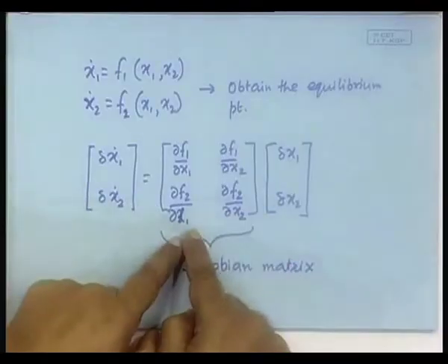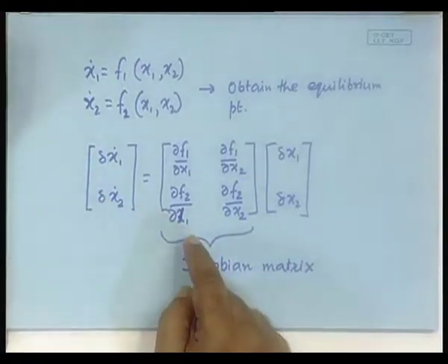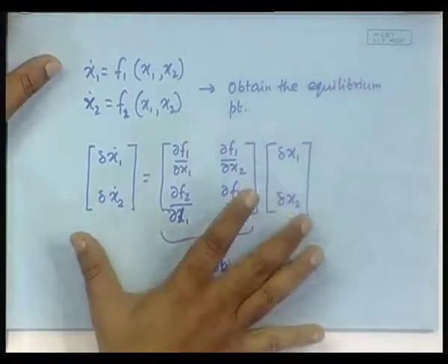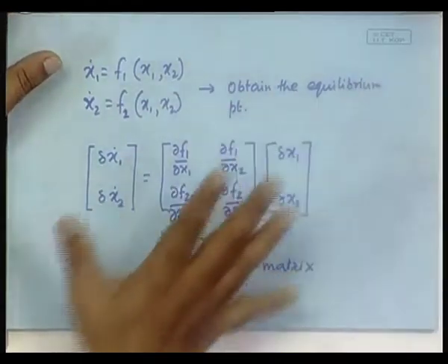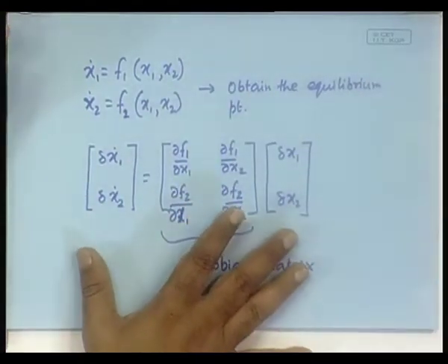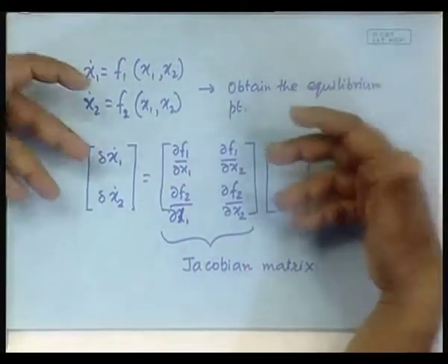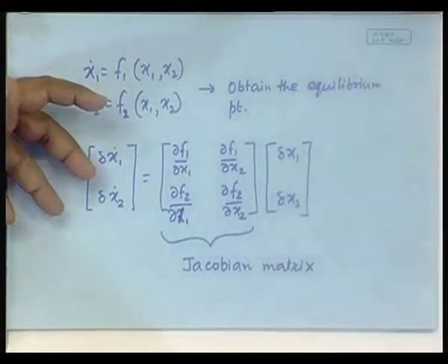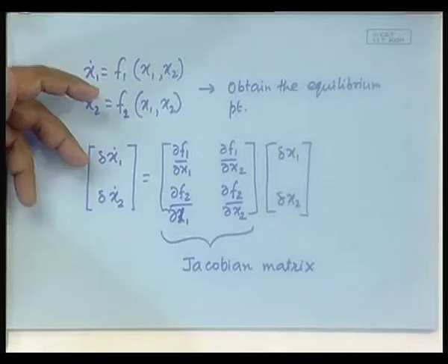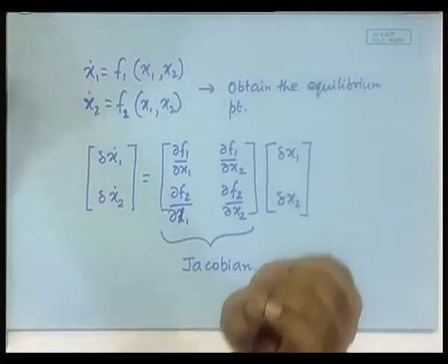If they are small, then this local linear approximation is more or less valid, and you will soon see that the moment you consider this equation, the solution and other things become very simple. That is why in most engineering studies we consider mostly this equation, but you have to understand that this equation is actually a local linearization around an equilibrium point, but the system was actually nonlinear.